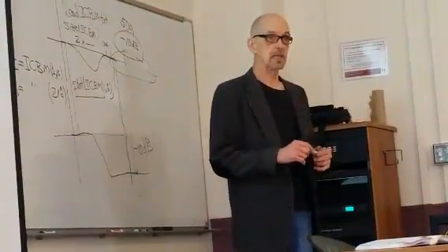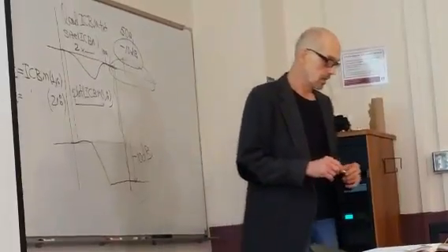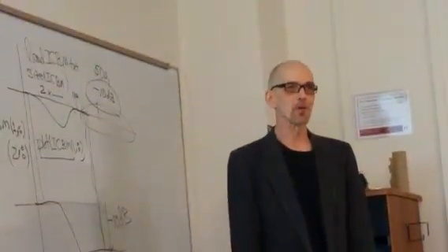Other questions? Yes. So for part B, are we using the transfer function that we did, or are we taking the other one? What else would you use? Oh, you should use the revamped one. All of it uses the reduced order transfer function. If you do it right, you should find that the reduced order FRF and impulse response are dead on. So at that point, keep it simple and use the simpler one.